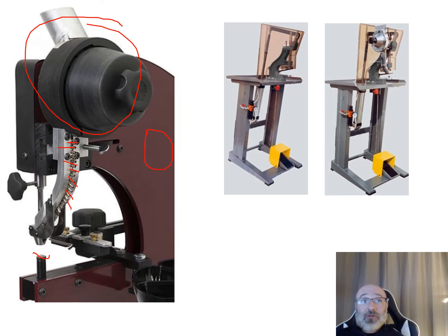And if you're doing large-scale production, sometimes it makes sense to do an investment and get something like this where you can speed up your process, where now I don't even have to feed the rivets in or set them in manually anymore. And a lot of times that is a lot of time. You're just putting your material down, reaching over here, grabbing the rivets, putting them in and going. Now I can literally just have all my leather pieces or whatever it is that I'm riveting lined up, step on the foot pedal. But the thing to think about is that this is still a manual machine in the fact that I am giving a mechanical advantage by stepping on it, putting my body weight onto that foot pedal in order to compress the rivets.